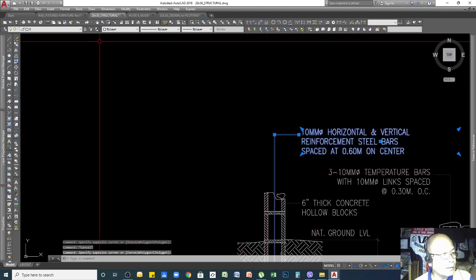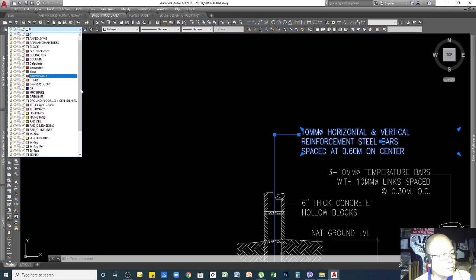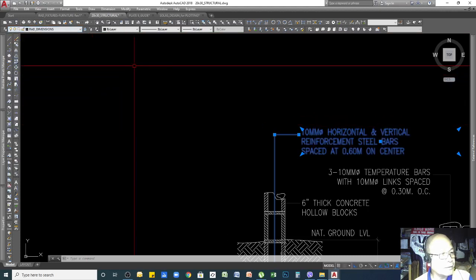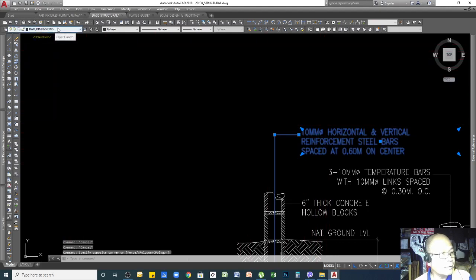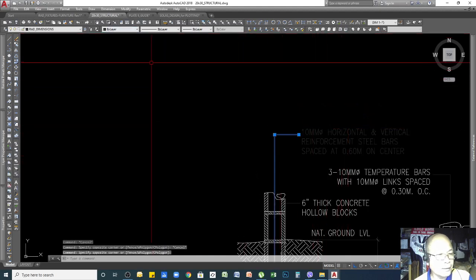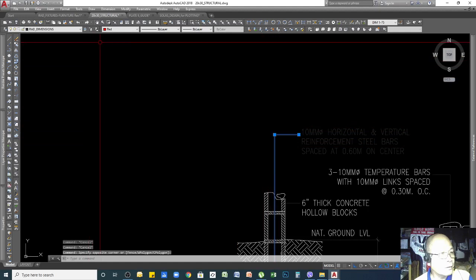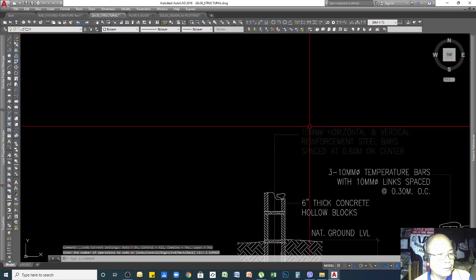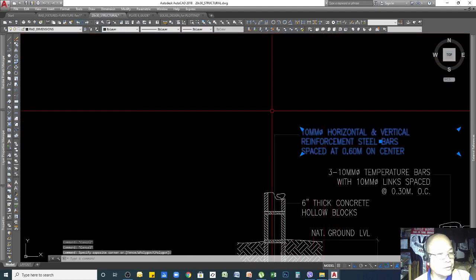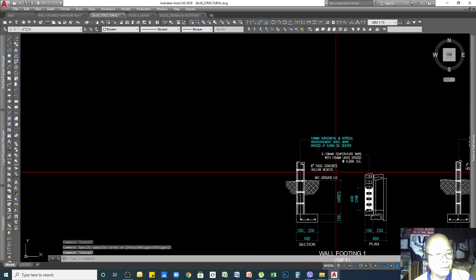So meaning it will look like this inside your drawing paper, and all you need to do is change the layer to whatever your layer is. See, when I click now, my layer RAD dimensions is showing. If I want to change the color, say I don't like gray, I will use red. Oh, sorry, this is fixed, because this is an extended leader line. Only this one you can change. Let's say you want to make that a cyan color, like that.